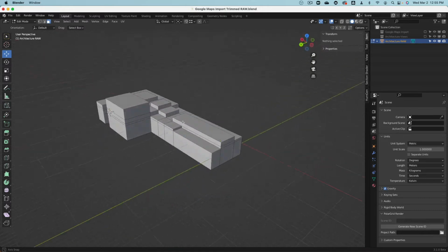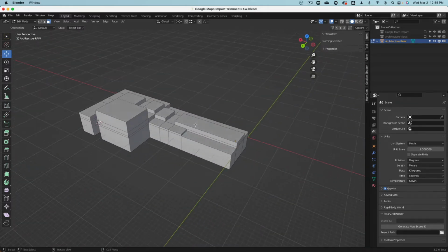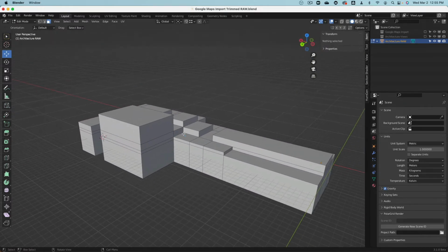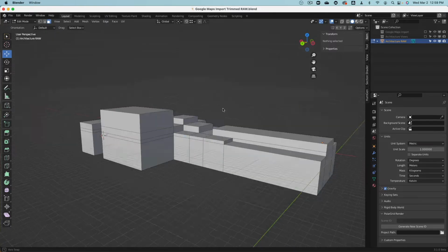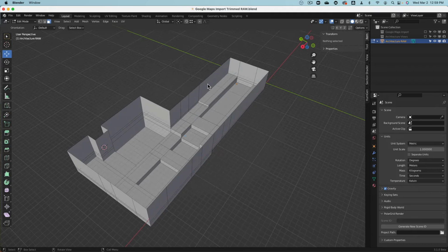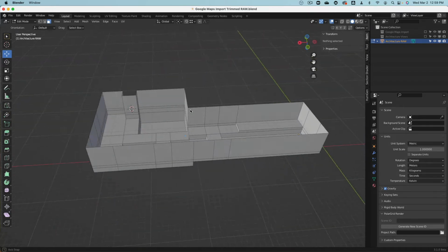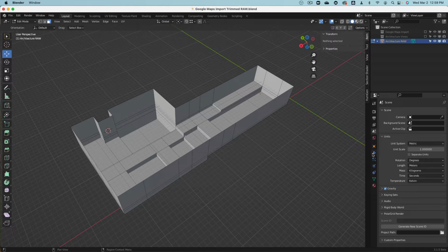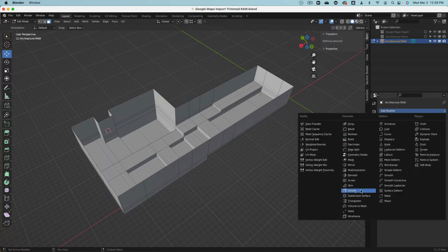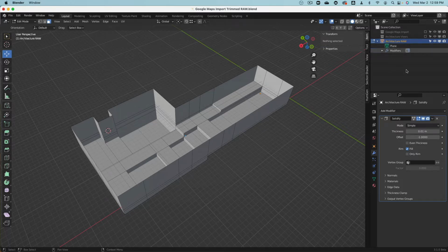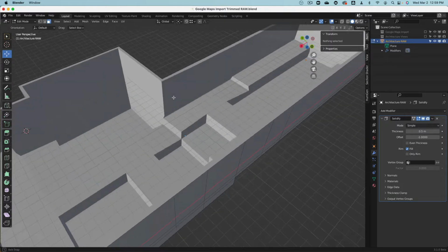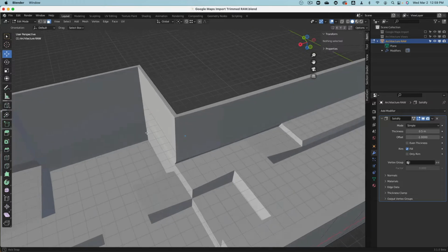Okay, I would say the basic modeling of this raw piece is actually good. And then we can take a look at what else to do. Well, this is a paper model. Obviously, that doesn't really work. We need wall thickness. So modifier, add modifier, and solidify modifier to this model. Thickness 0.5, so half a meter, 50 centimeters. That's massive, but for the moment it's okay.